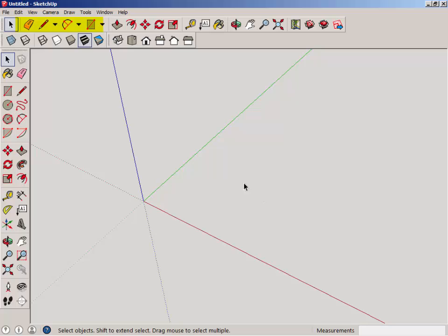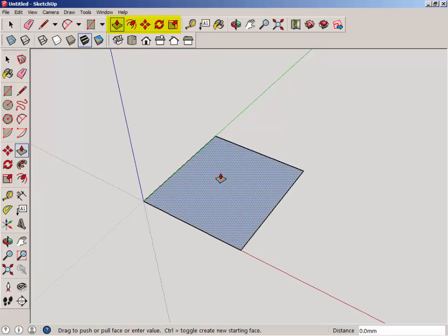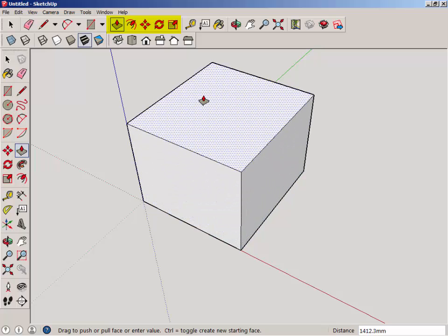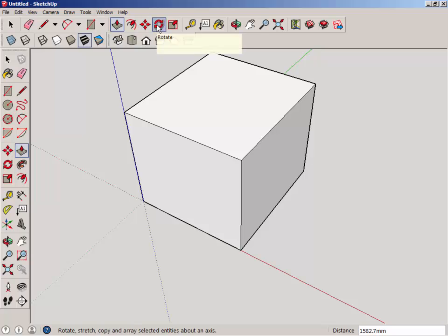After the selection arrow, the first four tools are for creation and destruction of elementary objects. We want to construct the base of our prism, in this case, a rectangle. Pay attention to how the rectangle snaps to the axes. The red tools perform operations on objects that exist. In this case, we are push-pulling, or I like to say extruding, a rectangle up to form a prism.